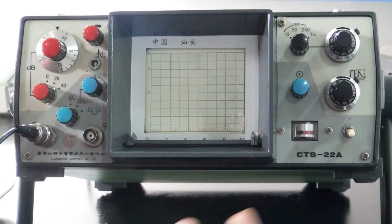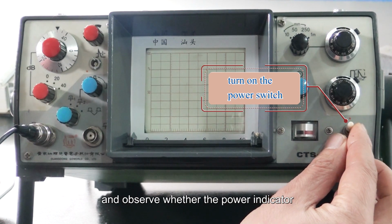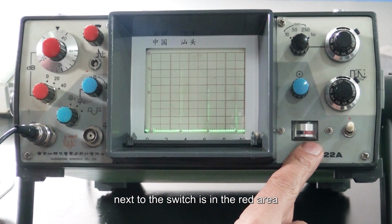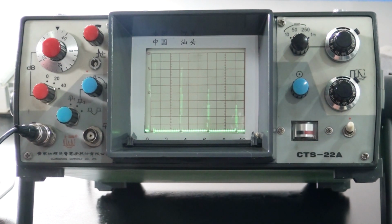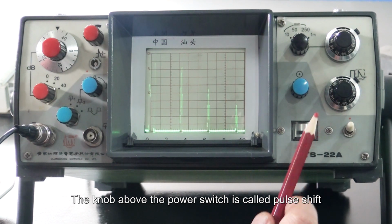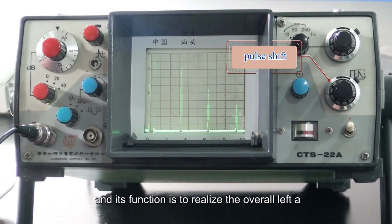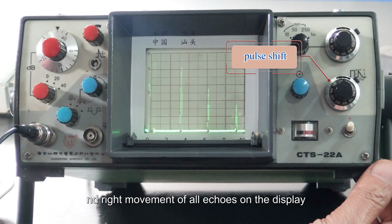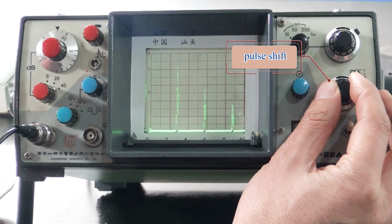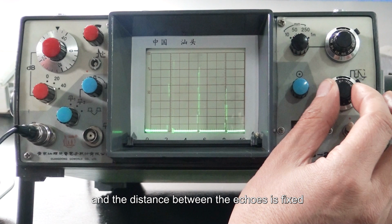After checking, turn on the power switch and observe whether the power indicator next to the switch is in the red area. The knob above the power switch is called pulse shift, and its function is to realize the overall left and right movement of all echoes on the display, and the distance between the echoes is fixed.